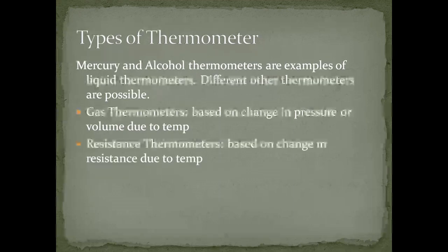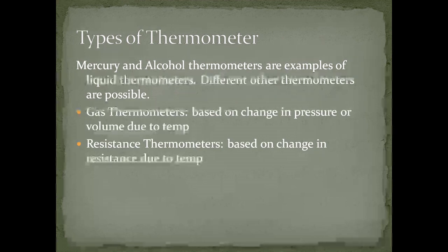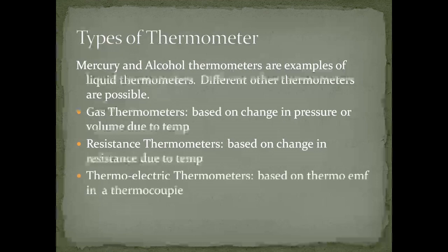Similarly, there are resistance thermometers. Digital thermometers are built using resistance thermometers. For example, if we use thermistors, the change in temperature also changes the resistance of that material, and we can assign different amplitudes of current to temperatures. This way resistance thermometers are built, and similarly thermoelectric thermometers.